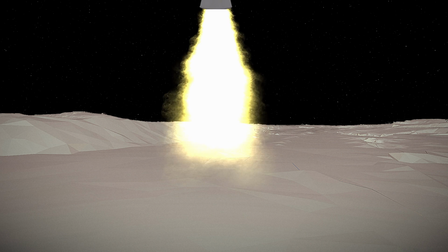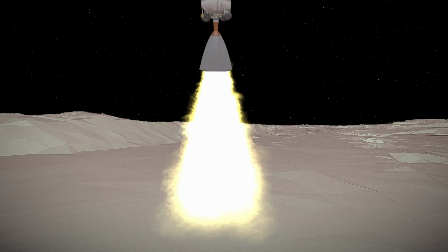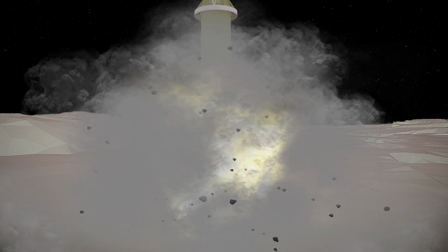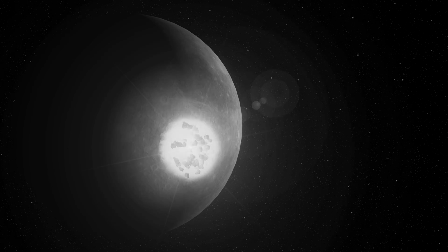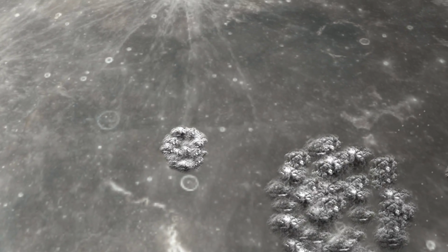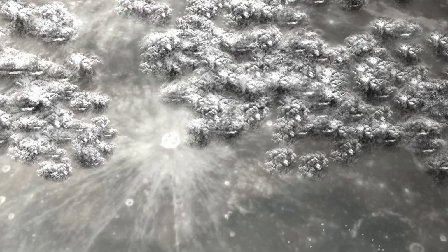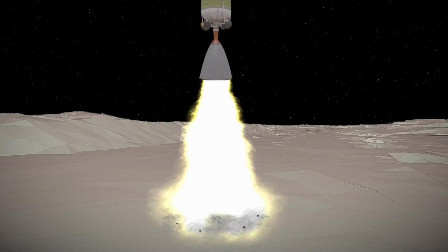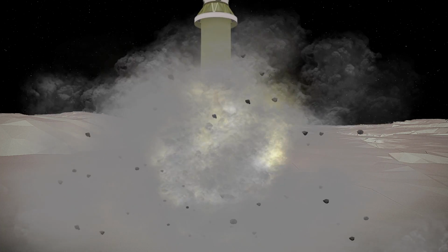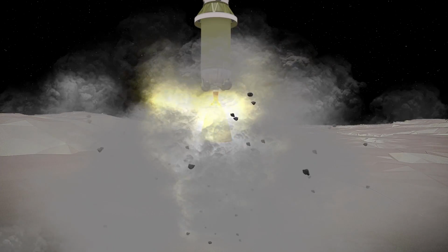As a retrorocket gets closer to the surface, it's going to start blasting the high-speed exhaust onto the surface. Unless it's a large, anchored solid surface like a landing pad, anything loose on the surface will be blown around. Over the billions of years of their existence, the moon and other rocky celestial bodies have accumulated a large amount of dust from asteroid and meteoroid impact on the surface. This dust, when blown up by the retrorocket, can damage sensitive scientific instruments on the spacecraft or even damage the spacecraft itself. The more powerful the rocket engine exhaust, the more damage can be done to the spacecraft.